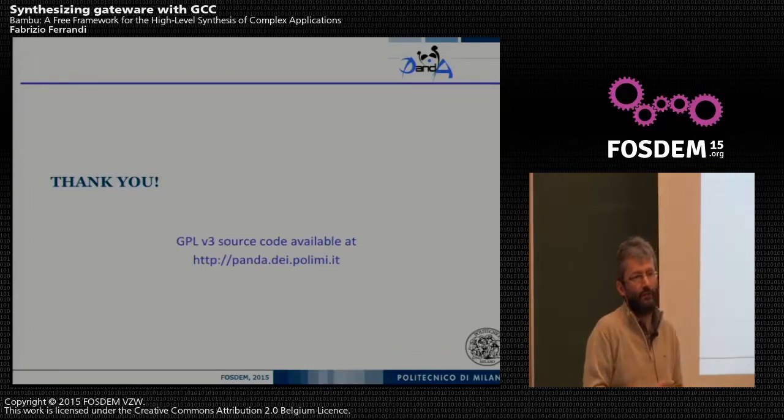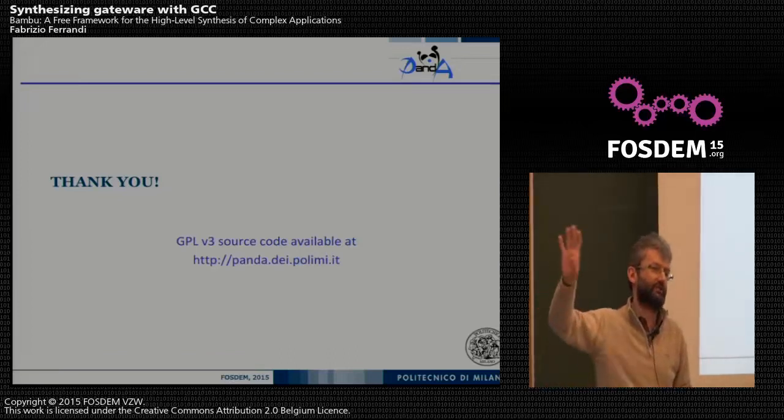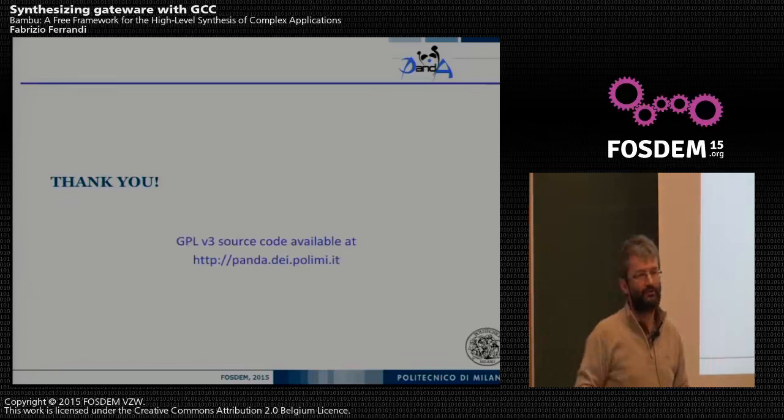I mean, it's a matter of designer fantasy. I did such things, for example, for floating point cores. Sometimes I start from a VHDL description of available floating point units, and I try to rewrite everything in C. Most of the time you have to deal with bit sizes, but that can be controlled in C through masking and saying that this is not greater than that, and so on and so forth. The compiler is pretty clever at that, since, for example, GCC 4.9 started to support value range, and so we just have to add bit value analysis, and so on and so forth.